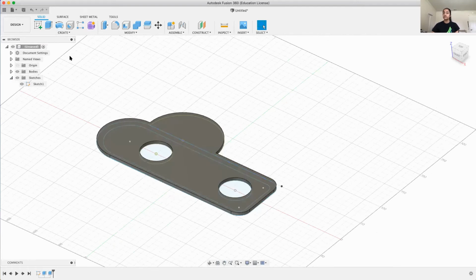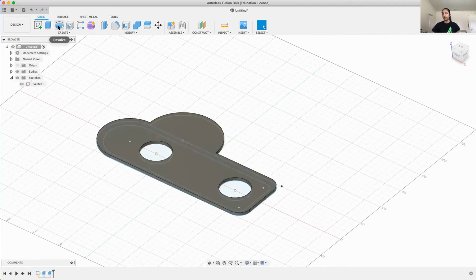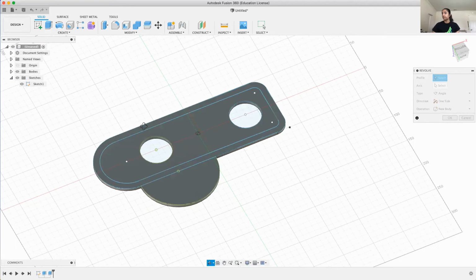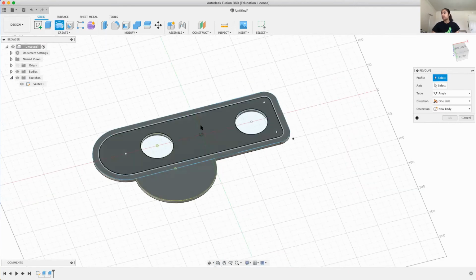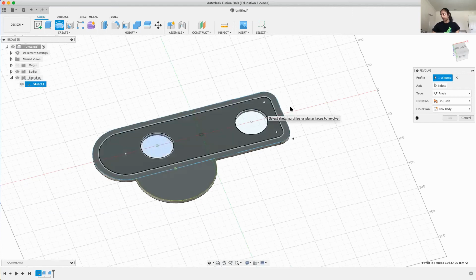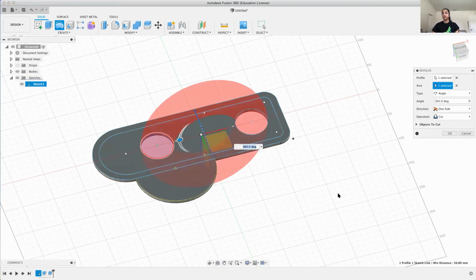There's another way to work with making something three-dimensional, and that is with this revolve feature. If you guys have ever seen the handle of something that looks smooth and curved, that's almost like you revolve a circle around some kind of center point and then it becomes like that, if you think about it that way. And that's exactly what we're going to do right now. So you see on the bottom of the sketch here, I still have my little axis here. I have a circle here I could work with. So if I just choose an axis, let's say I make it this point right here, which is the one I'd drawn in as construction geometry.